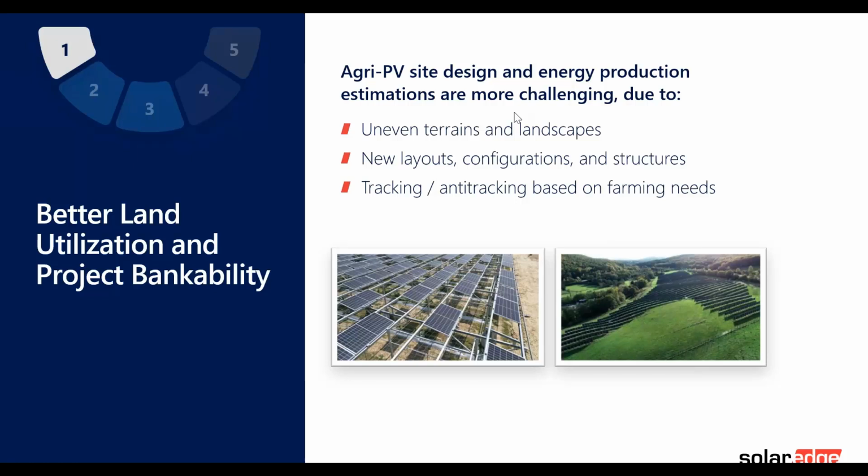And this really makes it more challenging to design these sites, and not just to design, but also to predict how much energy will be produced. And this is a challenge in terms of bankability, because if you do a new layout, if you increase pitch, if you suddenly need to optimize the sunlight radiation between crops and the PV modules, then it really makes it more difficult to understand how many hours during a day you'll produce energy, and how many hours during a day will be devoted to produce crops.